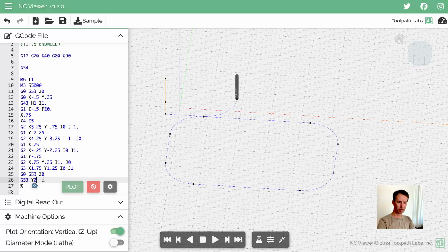All right, so we've done that. At this point, our spindle is still on, so we should probably do an M5. And actually, we could have put the M5 on another line, like we could have put the M5 here when we retracted Z. An M code can be on the same line with G codes. It can be on its own line.